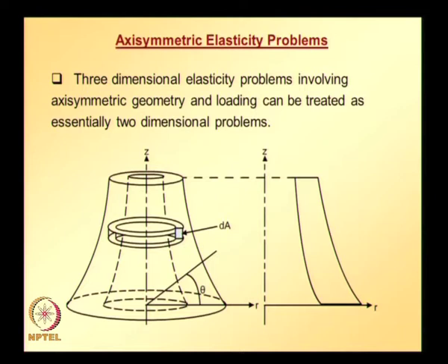So basically, 3-dimensional elasticity problems involving axisymmetric geometry and loading are as shown in the figure here. A typical situation with the z axis as the axis of revolution is illustrated in the figure. For this kind of situation, 3-dimensional elasticity problems can be modeled as 2-dimensional problems.